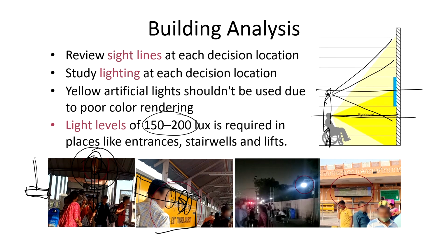If there isn't enough natural light, extra lighting may be needed for the signage to be read. However, glare should be kept to a minimum so that the messages can be seen, especially by people who are blind or have low vision.